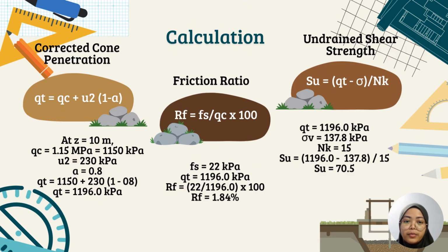The increasing pore pressure confirms saturated clay conditions. However, soil strength improves significantly with depth, and the layer at approximately 10 meters offers better bearing capacity for foundation support. Therefore, ground improvement techniques or deep foundation systems should be considered to ensure long-term structural stability. That's all for me. I will pass to the next presenter.